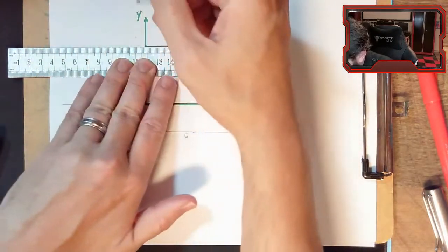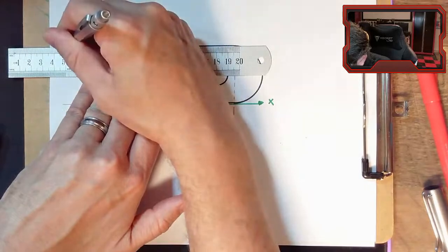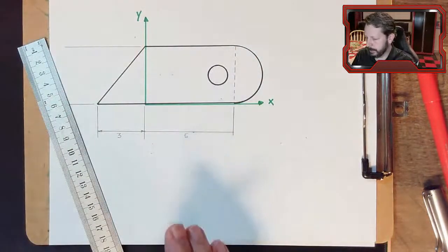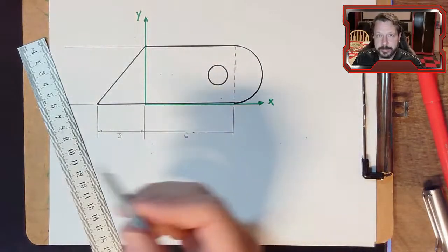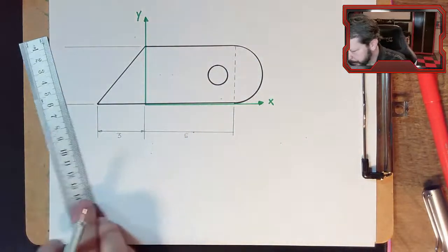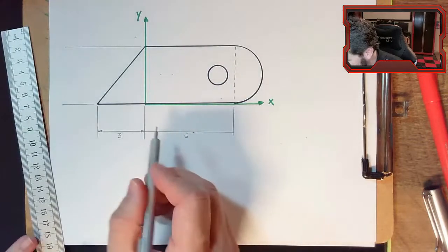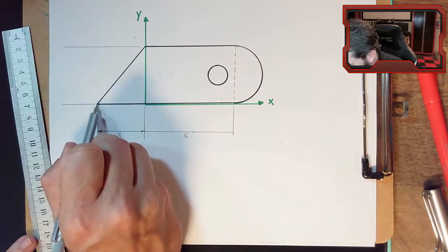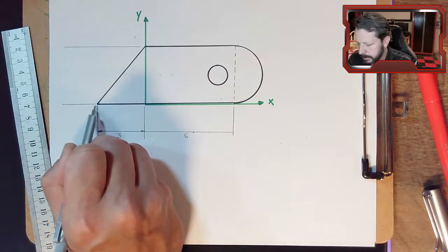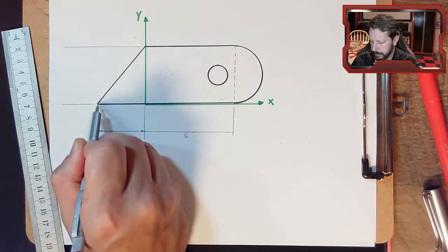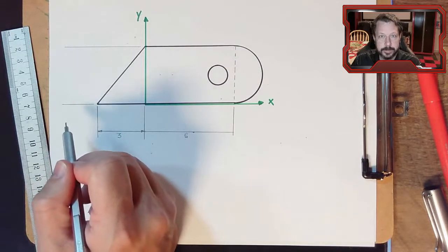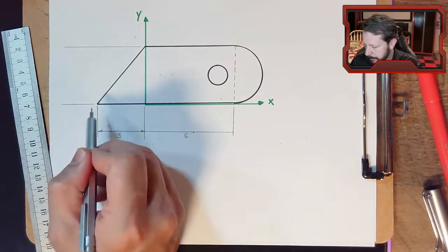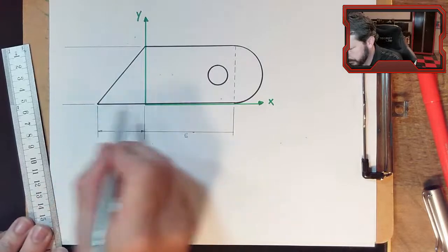So these little lines I'm drawing right now are called leader lines when you're drafting. If you're actually drafting the part by hand, I don't know if people even still do that, but if you are, then the leader line has a gap, maybe a 1/8 inch gap, between the part, which has these darker lines, and the leader line, which is going off to some dimension somewhere. So there's a little gap there. That way it's not confusing whether that is part of the drawing or not.